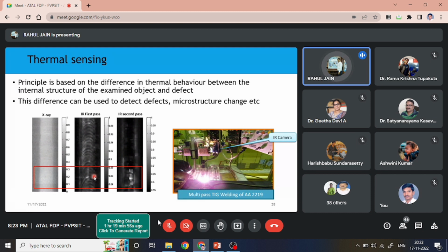If it does not melt, it will not create a proper first layer. If it is not creating a proper first layer, the bonding between the first and the second layer will not happen, leading to interlayer porosity. If the temperature is too high, the viscosity of the liquid will be very low, which will not be desired. This is one problem. What is the second problem?